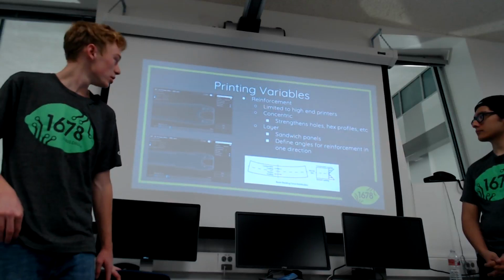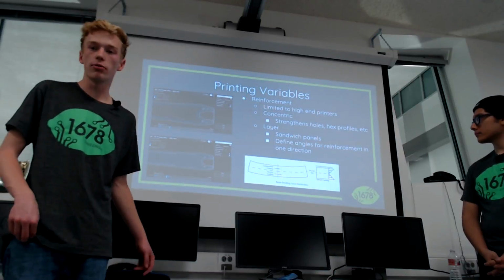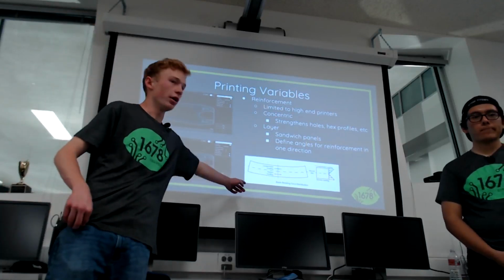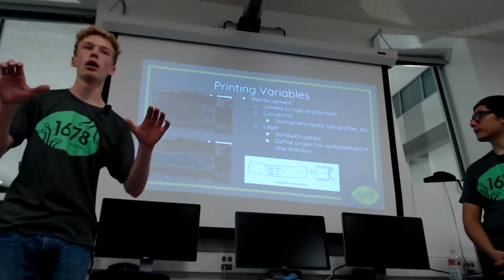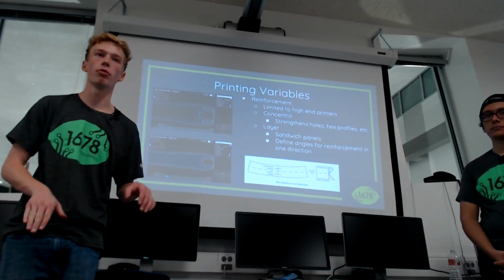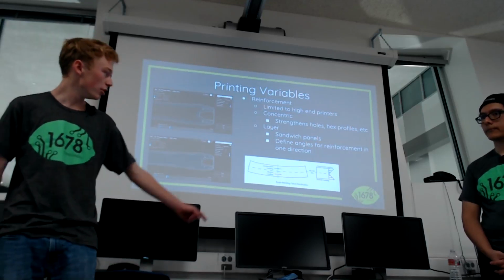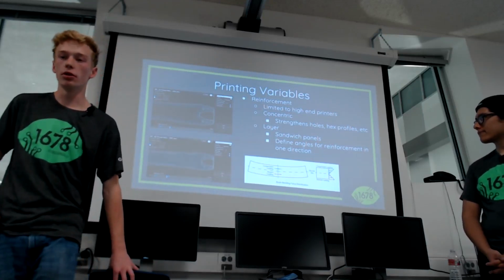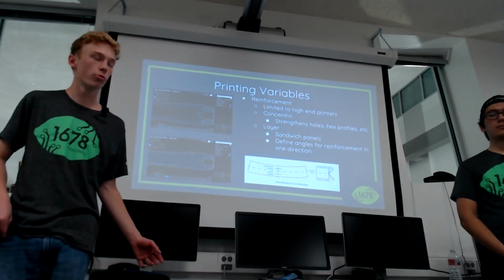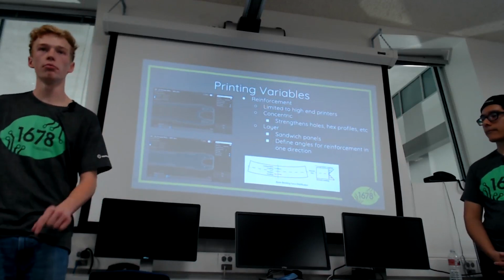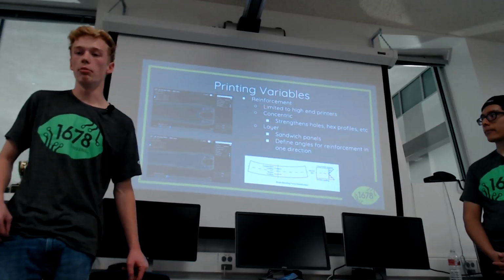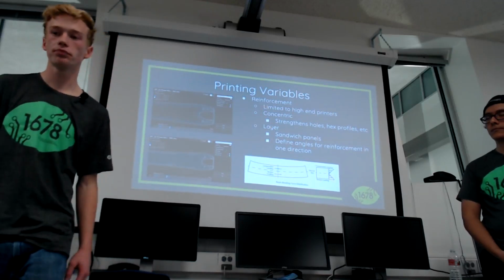For maximum efficiency, the best way to do the reinforcement material is what's called a sandwich panel. If you look at this diagram right here, the idea is anytime you're flexing a part, anytime you're trying to bend it, you're always going to have the most forces at the very top and the very bottom of your part. It's where the most compression and the most tension is going to be. You can kind of see that in this diagram here. And so in general, you want to be maximizing your material. If you add a thin layer of reinforcement material at the very top and a thin layer at the very bottom, that's where these forces are going to be the strongest. The material is going to be doing the most work possible. And it can really increase how stiff these parts are.